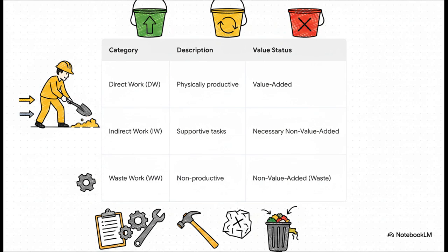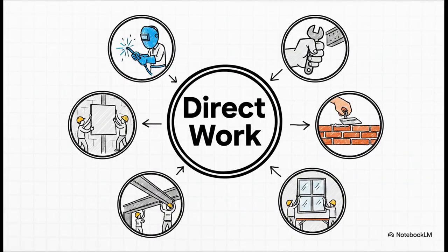Any action you see on site falls into one of these. Direct work, that's our pure value-added time. Indirect work, that covers all those necessary support tasks. And waste work, well, that's the pure non-value-added stuff we want to get rid of. Let's dig into these a little more.